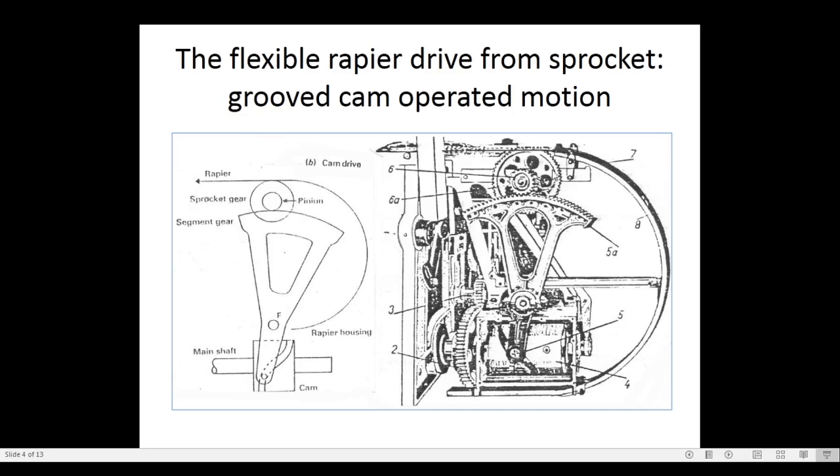So see here the figure, three-dimensional figure we can see here. So here the cam moves, the drive comes from the main shaft, the pin is there at the bottom side in the groove. So as the main shaft rotates, this will move clockwise, this gear pinion will move anti-clockwise, this will move clockwise and this will move opposite, and the backside gear is moving one time clockwise.